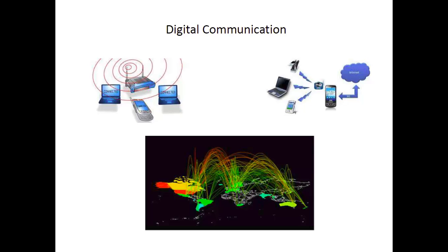For wireless, you're directly designing signals to be carried by electromagnetic waves in such a way, like I said, that will be robust to noise. And one part of that is that a wireless signal can bounce off many paths to get to its destination. And this appears as a bunch of echoes in the received signal. And echo cancellation is something that's very well handled and understood through the Fourier transform, which, I guess, is the first time I've mentioned that so far, but that's the big emphasis of this class and what you're going to become very familiar with.